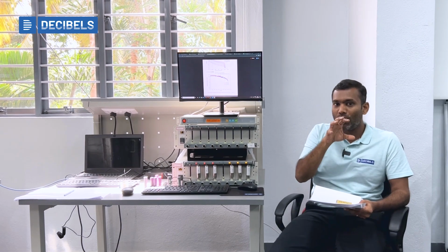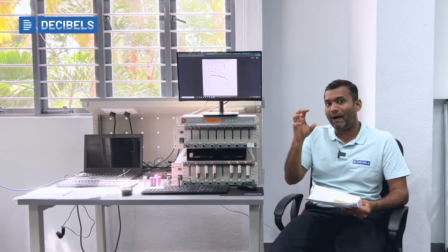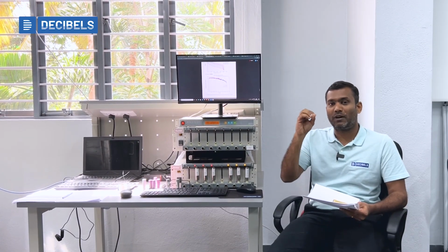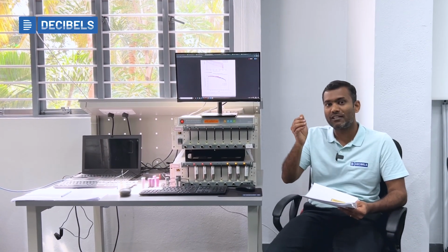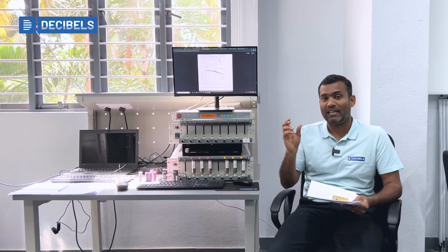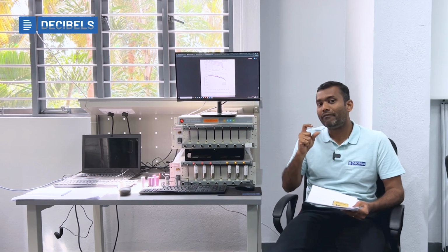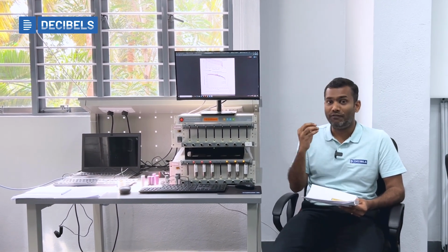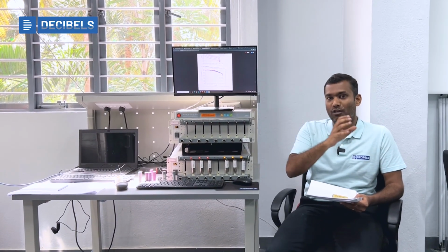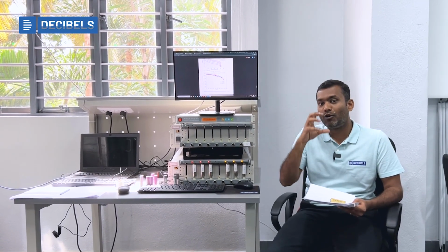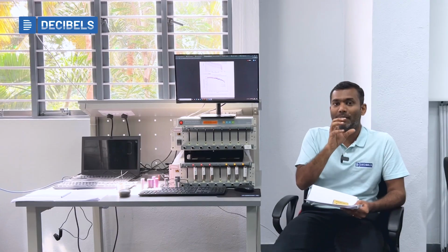To understand all of these characteristics and the behavior pattern with respect to DOD, temperature, C rates, and also age, we perform a capacity test for a cell, and we understand its intrinsic nature and behavior. This data is very useful if you're developing a BMS algorithm. You're defining for the cell that this is your operating range, this is your output capacity, and you relate the SOC of the cell with respect to the capacity of the cell.